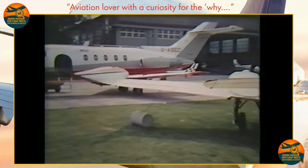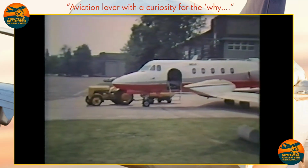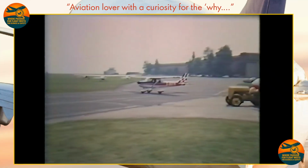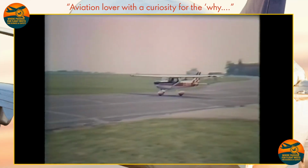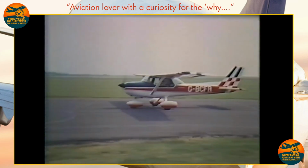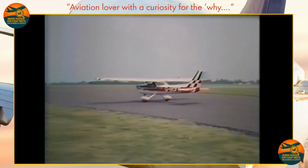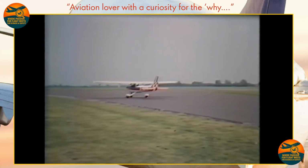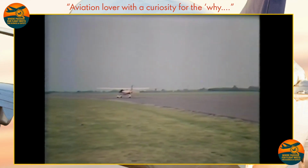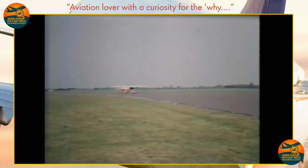In determining just how an aeroplane flies, and the forces acting on it, its natural behavior and the ways in which we can control it, let us go to the grassroots of aviation, and from a considerable range take a typical light aeroplane as our example, the Cessna 150 Aerobat. It weighs 1,600 pounds fully loaded and is supported in flight by a wing spanning just over 32.5 feet. This wing, like every other, exerts a lifting force in level flight exactly equal to the weight of the aeroplane.